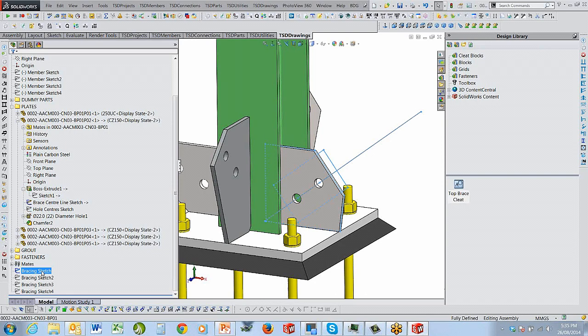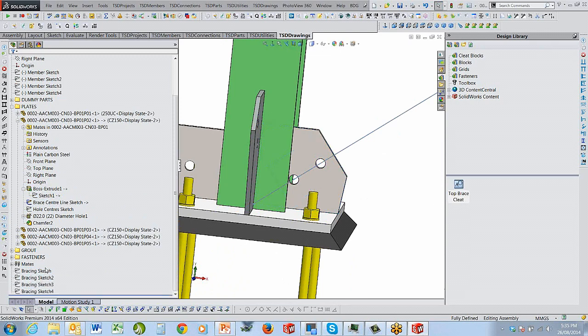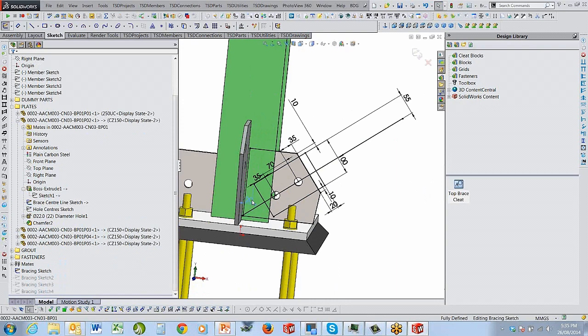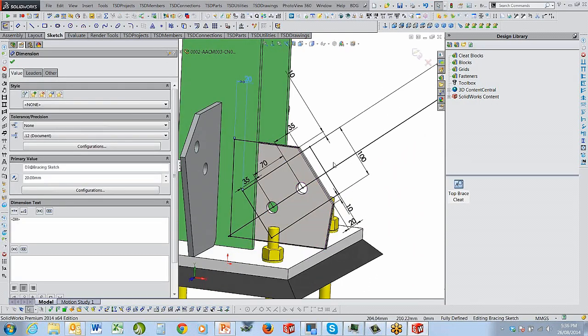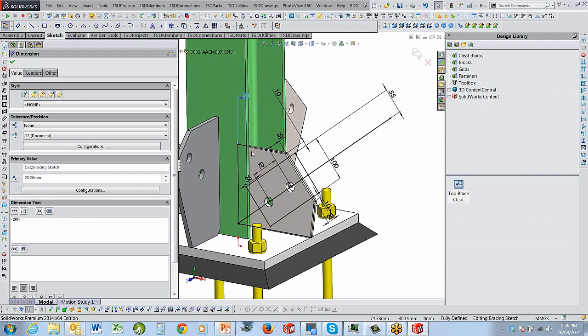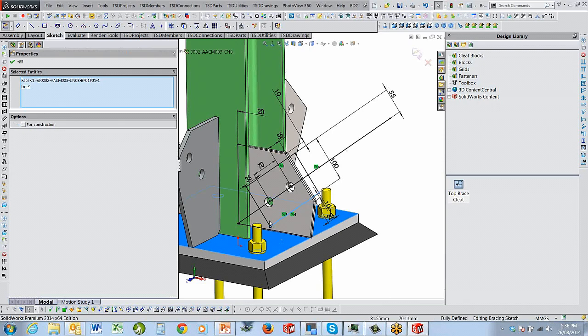What I mean by that is, if I open this sketch up and edit it, you'll see that the clearance for this particular brace that I've drawn in here, which is just an angle brace, and it's got a gauge and 100 mil. That whole brace that's set up in that driving sketch has a 20 clearance on one edge. Obviously, if it becomes acute from the base plate to the slope, you want to put your 20 clear on that edge. So you literally have to switch between the other.